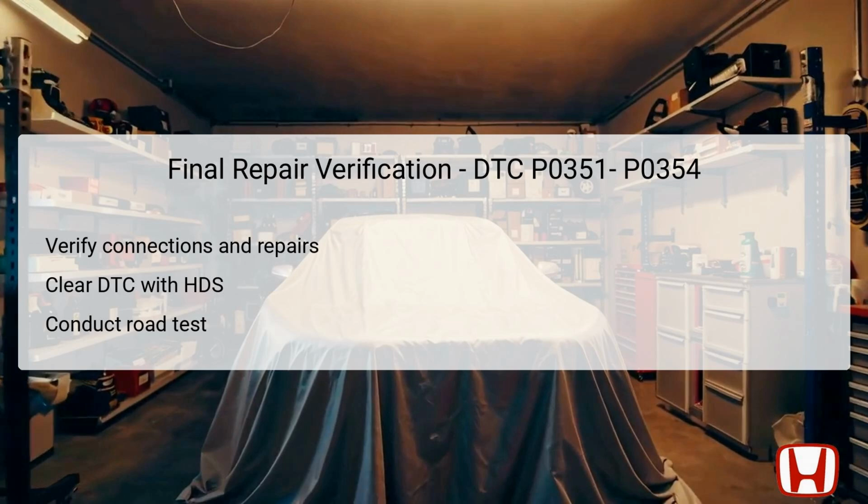After completing repairs, a rigorous verification process is needed to ensure everything functions correctly. Begin by thoroughly examining all connections and repairs made throughout the troubleshooting process to confirm they are secure and intact. After verifying the connections, use the Honda Diagnostic System HDS to clear any DTCs that may have remained after the repairs. Following this, conduct a road test to assess vehicle performance under normal driving conditions.